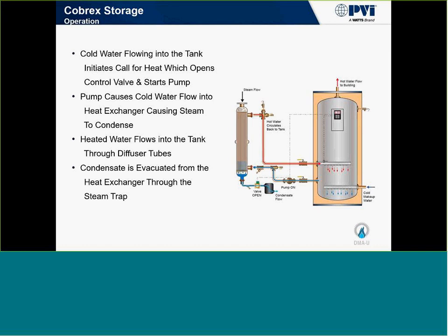When the T-stat is satisfied, we will actually run that pump for an extended 1 to 2 more minutes, which is going to fill the shell, or actually the tubes, back up with condensate, because there's no call for hot water. As soon as the storage tank is satisfied and the heat exchanger is filled with condensate again, the pump shuts off, and we wait until we have a demand for hot water, in which case the system would kick the pump back on and create more hot water. What this also does is give us the ability to raise or lower our temperature inside that tank.